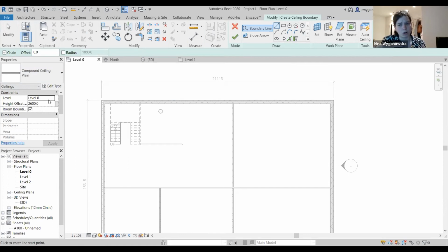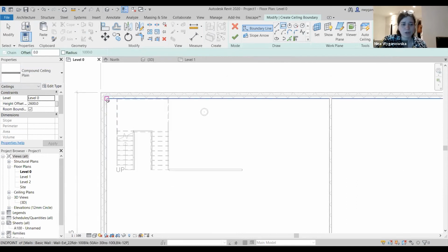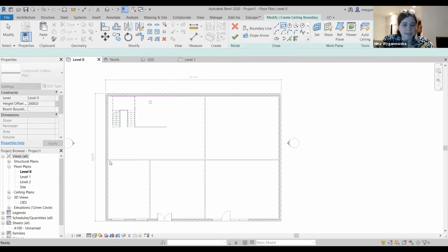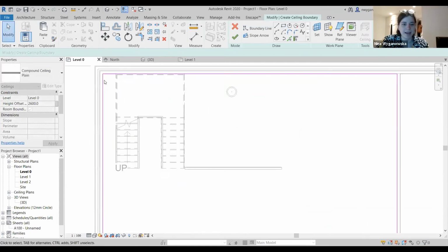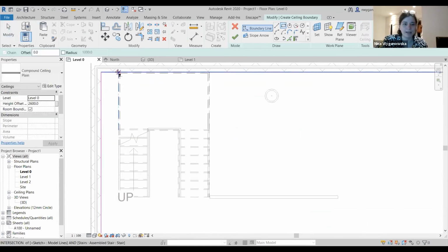And it doesn't always work, because if you, for example, offset your walls to be lower or higher and they don't hit, then the ceiling is going to be adjusted and put into the whole building on the same level and on the same height. So I'll just drop a ceiling here, and remembering that we have our stair opening, remember to always cut an opening for your ceiling.